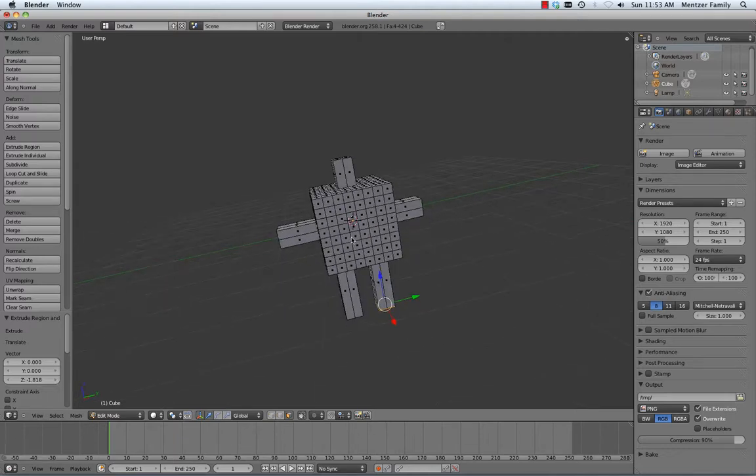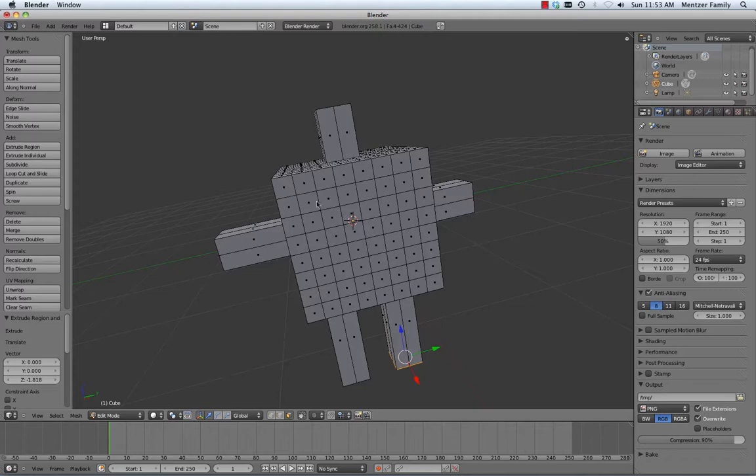Now that we're here, let's look at a couple of things in closing when we're working with grabbing specific points or edges or faces in edit mode. A couple tools that you can use. Again, Control-Tab will let you pick what type of control you're going to grab, a vertex, an edge, or a face. So I switched to vertex right there. G will let you grab that point and move it in space. S will let you scale it, and R will let you rotate it.